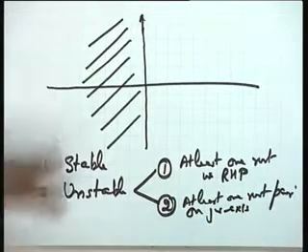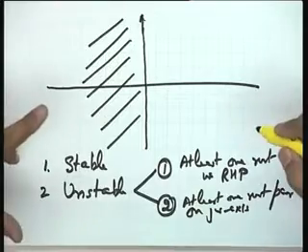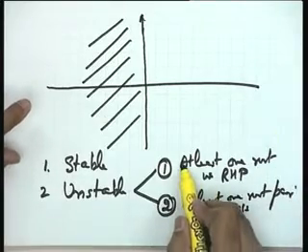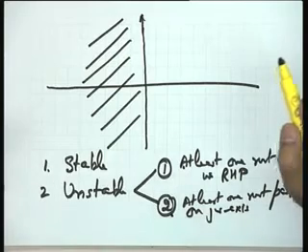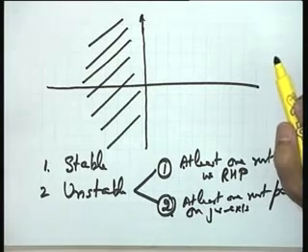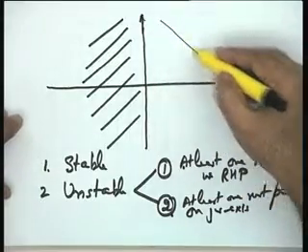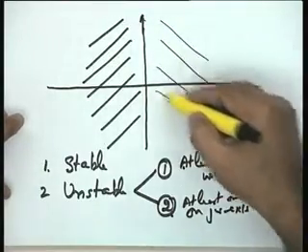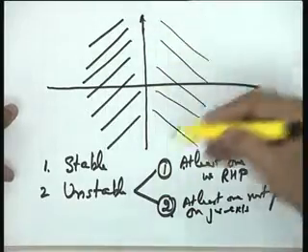Please see, both of these could happen. So, this is the minimum condition. In that particular case, what will happen? This condition or this condition gives you a growing mode in the response, and a single growing mode can definitely turn the system into an unstable system. So, this is the situation: at least one root in the right half plane, or a pole pair on the imaginary axis will definitely lead to a growing mode.